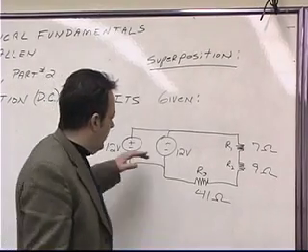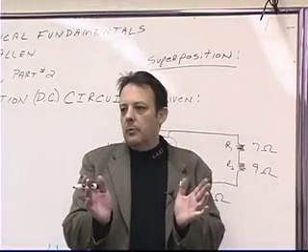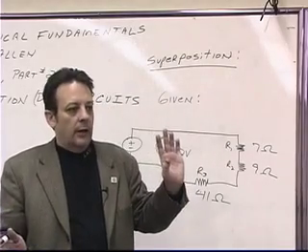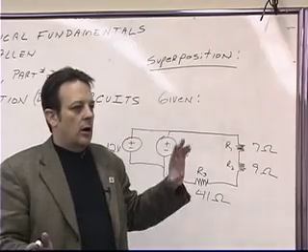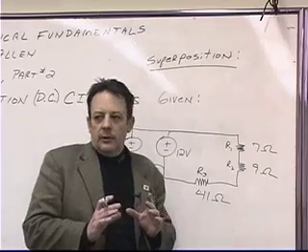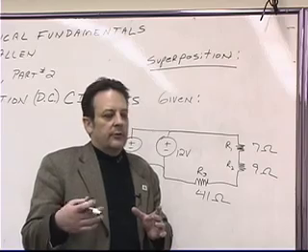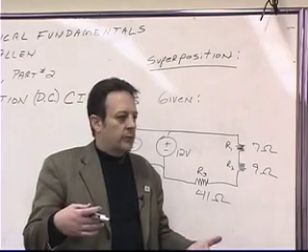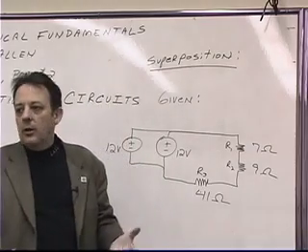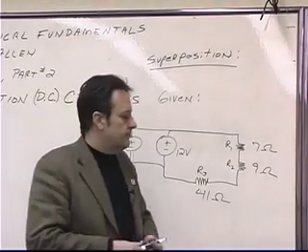Okay? The only thing that is additive is what? The current sourcing capability of the batteries. In other words, if there's a load that requires a lot of current, like for instance, you've got a car in very cold weather and your starter motor needs an extra boost of current to crank over and start your engine, then instead of having 800 cold cranking amps, by having 2 batteries hooked up in parallel, maybe you'll have 1,500 cold cranking amps for 3 or 4 seconds.